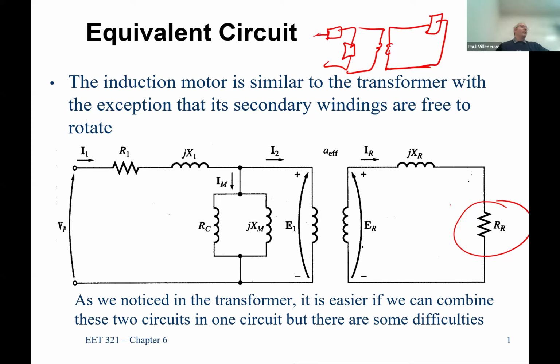Anybody buy that for $1? Anybody believe that? What is the motor rated for? 50 horsepower, 100 horsepower? Can I convert that to watts? Yes. What does the power consumption in a resistor look like? What are the units for that? Watts. So watts equals watts. As long as I have an equivalent resistor that is equivalent to the amount of mechanical power out, the circuit works really well. So here is our transformer circuit, modified to be a motor.